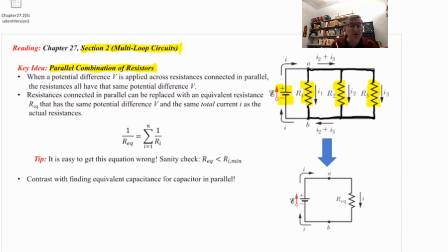Notice that if you were to insert any kind of circuit element in here, like in this position, if I put another resistor right there, that would spoil the parallel connection between R2 and R3. You can only have plain old conducting wire connecting them at the top and then connecting them at the bottom. And then they're put directly across something, in this case, a source of EMF.